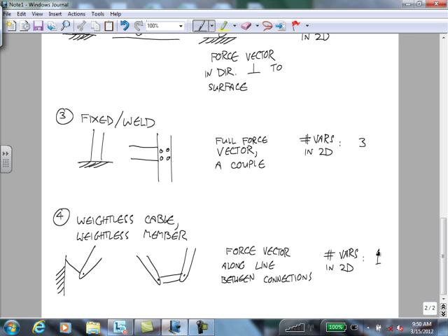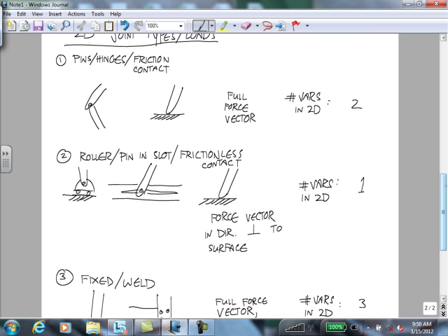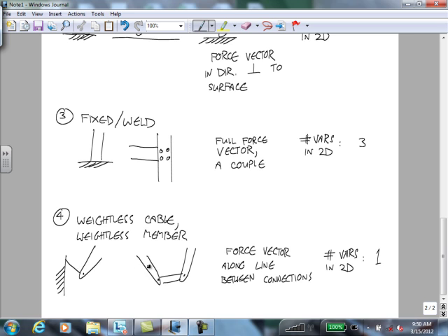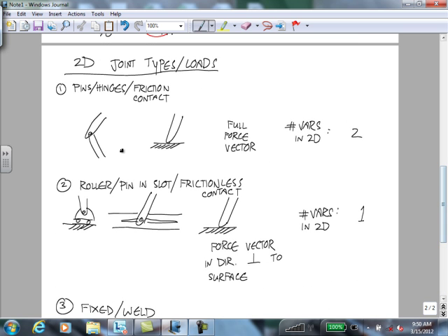Well, so what you do actually is the variables, all the math is just the same, but then after you get your answers, you need to inspect it to make sure it makes sense, okay? So in this case, we have 2 variables, right? If we end up with a force saying that it's pulling the member down, we know something isn't working. Our model, like usually all that means, if you're doing a problem out of a book or whatever, it means you did something wrong.